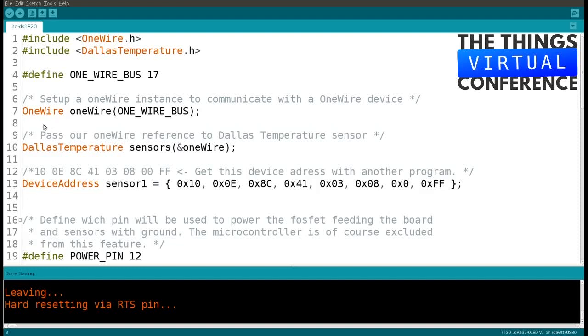So, in this case, they install the SSD1306. That's for the display, if you want to use a display, for instance the Heltec or TTGO. Most of the displays that run over I2C, you can use this SSD1306.